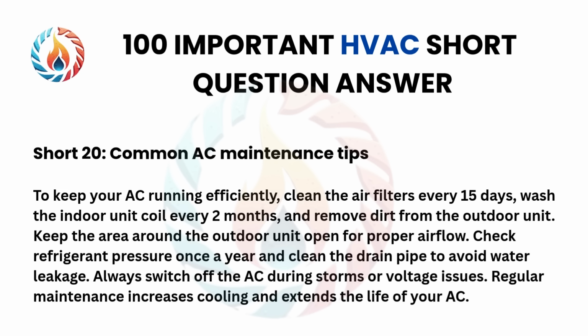Short 20. Common AC maintenance tips. To keep your AC running efficiently, clean the air filters every 15 days. Wash the indoor unit coil every 2 months, and remove dirt from the outdoor unit. Keep the area around the outdoor unit open for proper airflow.